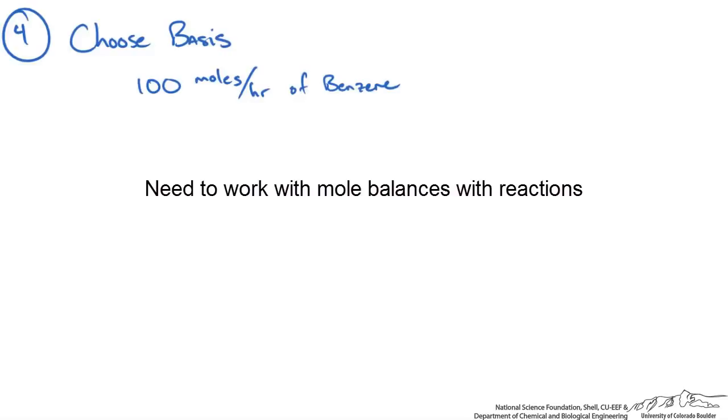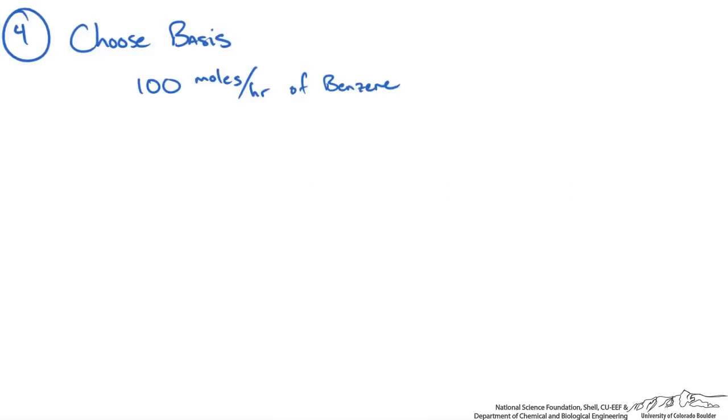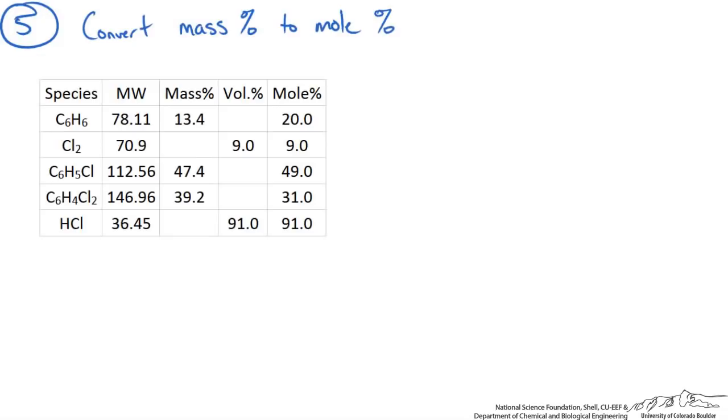So let's first determine the mole fractions of the components to use in our material balances. Now there are different ways to approach this, either using an average mixture molecular weight and converting using that value, or a step-by-step conversion going from our mass fraction to the amount of moles, and then from the amount of moles to a mole fraction. Now whatever method you choose, you should get the following values that I've written in this table. Now I'll step you through the first one.